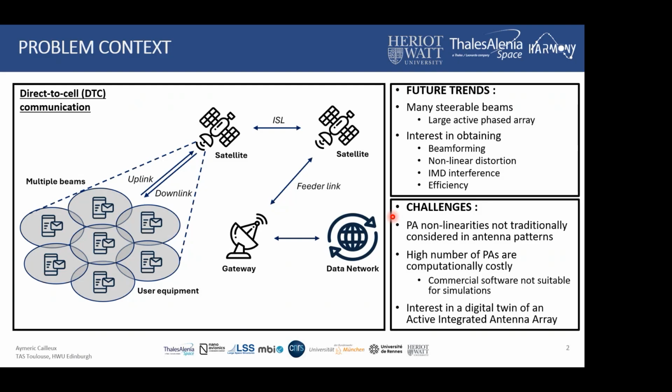As you can see in the literature, most of the antenna pattern and radiation pattern analysis are done without the PA nonlinearities. The reason is because when we increase the number of power amplifiers, we can start to have some issues in terms of convergence and also in terms of computation time. And yes, most of the commercial software are actually not suitable for these simulations. That's why we had this interest in a digital twin of an active integrated antenna array.